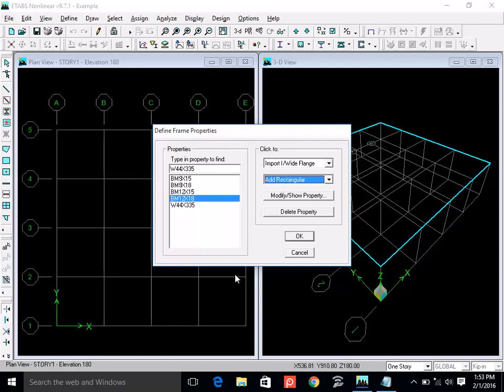It was the time when we had an earthquake in 2005. So we submitted the first design on zone 3, and then earthquake came. And then we had to revise our design completely on zone 4. Although Rawalpindi is not in zone 4, but still they wanted that it's a hospital, it's an essential facility, so we want some higher zone consideration. So that's why the sizes were too big. More of a column, more of a wall than a column. But except that, I never have experienced that somebody used 9-inch thick column.